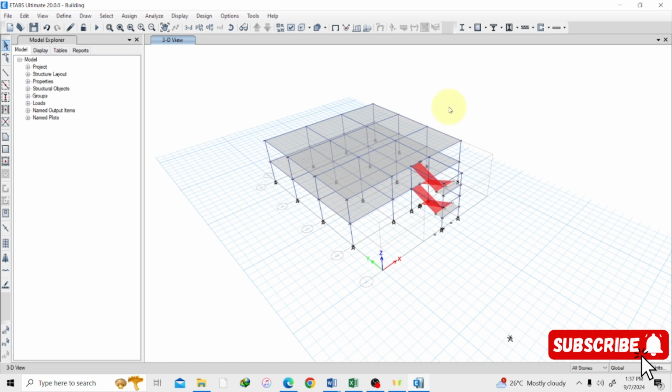So first of all, is the slab I'm going to mesh. So I'll have to select each and every slab, because I'm going to assign a mesh to that slab. You know that before we assign a command to a member, we have to select it. So you can go through by selecting each slab one by one, but it's going to take a lot of time.